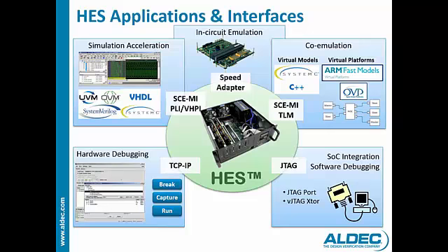Having the SCE-MI and transactional level model wrappers allows connection to the SystemC environment, which is co-emulation, and the possibility to connect to different platforms such as the ARM virtual platform or the Open Virtual Platform, or even virtual models that are SystemC or C++ based. So basically any application that can be developed that supports SCE-MI interface will act as a virtual peripheral or model.